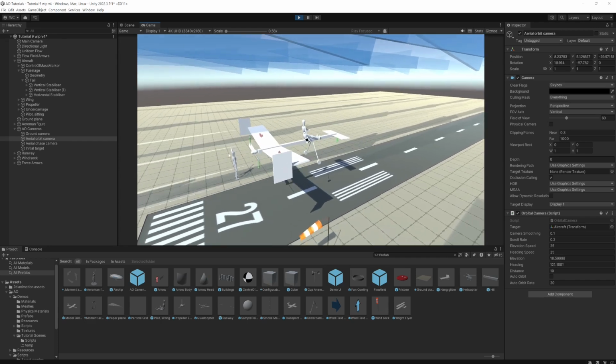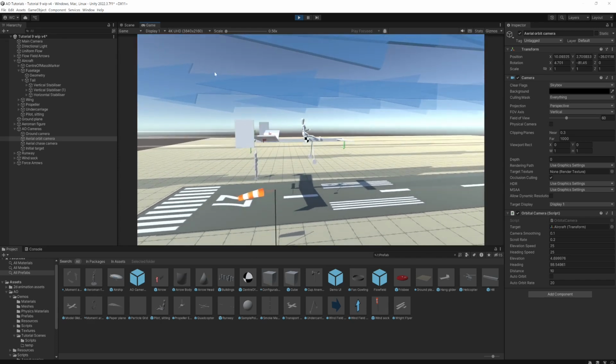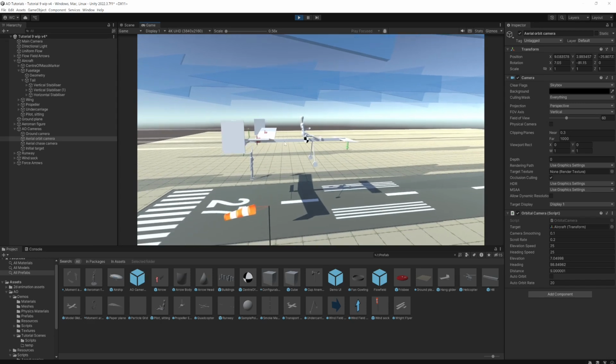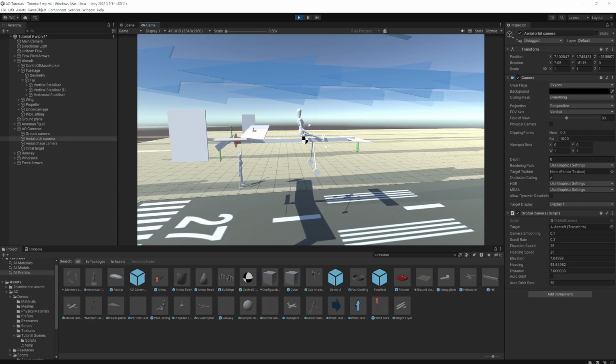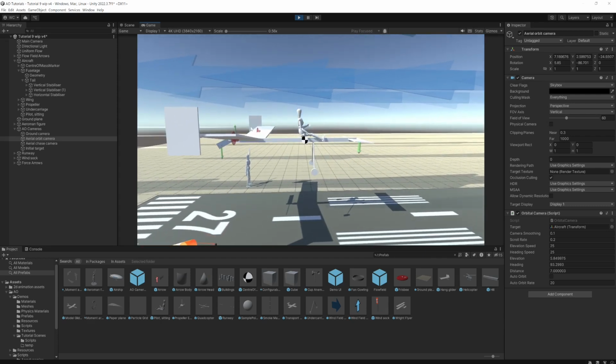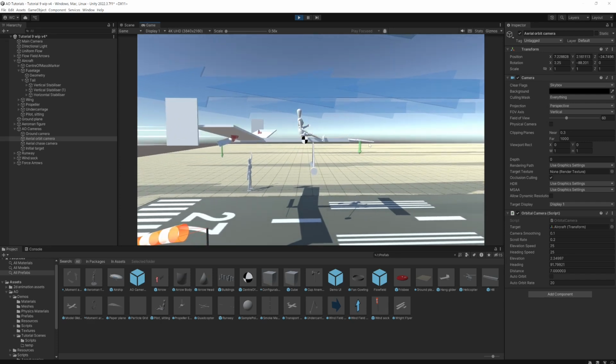We can see there that our wing is at 0 angle of attack. We've got plenty of wind, we can see on the windsock. But we notice that just in terms of the basic balance of the aircraft, there's no lift on the wings, but we've got a down force on the foreplane. That foreplane was set at that angle because previously it was at the back, and that's how we balance the aircraft. Now it's at the front. If we've got any lift on the wing, we need a lift force on the foreplane to balance that. At the moment, that's going to push the nose straight into the ground when we've got lift on the wing. What we want is to lift up the nose. Just from eyeballing it, we can see that the angle of that surface is going the wrong way.